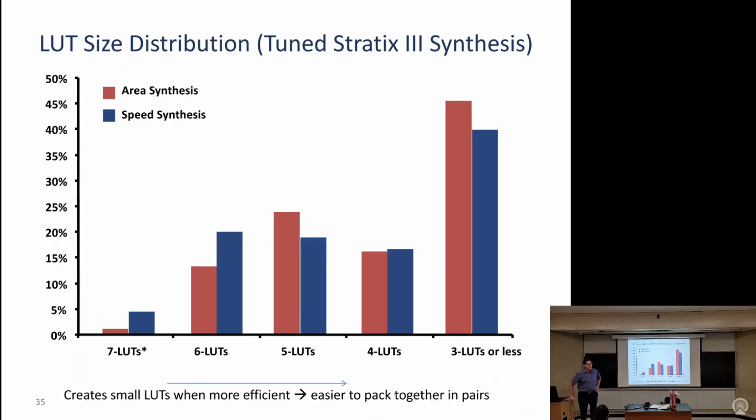Does that make sense? So I guess it's not like multiplexing 2 different inputs to a specific package. Well, it is steering one. Let's say you have one multiplier, but you have 2 different things you might want to feed to that multiplier. So you build a multiplexer in front of the multiplier. And the way you build that multiplexer in front of the multiplier is using the logic block, which is LUTs. Okay, so you're actually programming the LUTs.